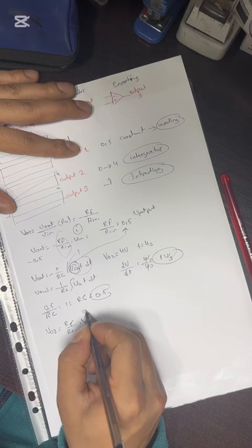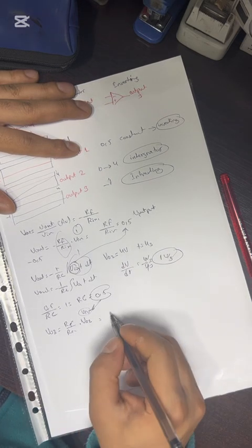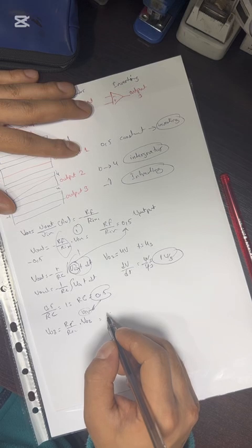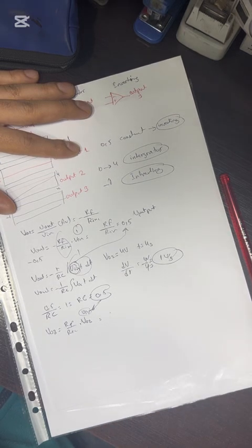Putting in the slope value, 1 times minus 1 gives constant minus 1, meaning that the ramp has been converted into a constant, so the third stage effectively acts as a differentiator, giving a constant in the control system. So it is an inverting amplifier with gain of minus 1 acting on a limited signal.